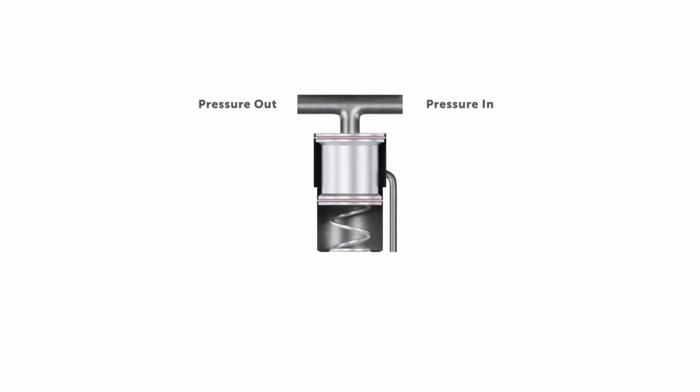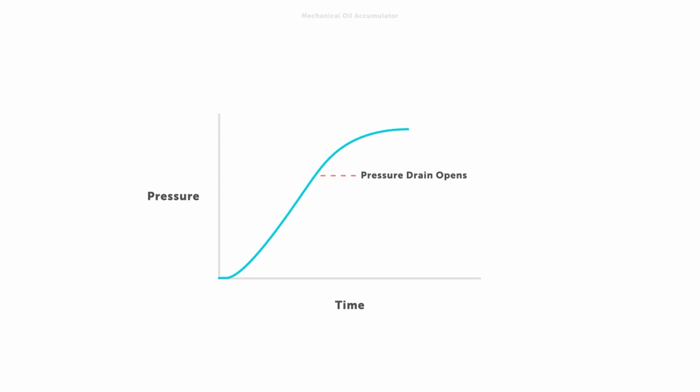The accumulator has a valve and spring, so as pressure increases, the fluid acting on the valve compresses the spring, which as it travels, exposes an orifice that lets fluid bound for the clutch piston bypass it and drain back to the pan. This bypass increases as pressure increases, slowing the rise of pressure at the clutch piston and making its actuation less like an on-off switch.